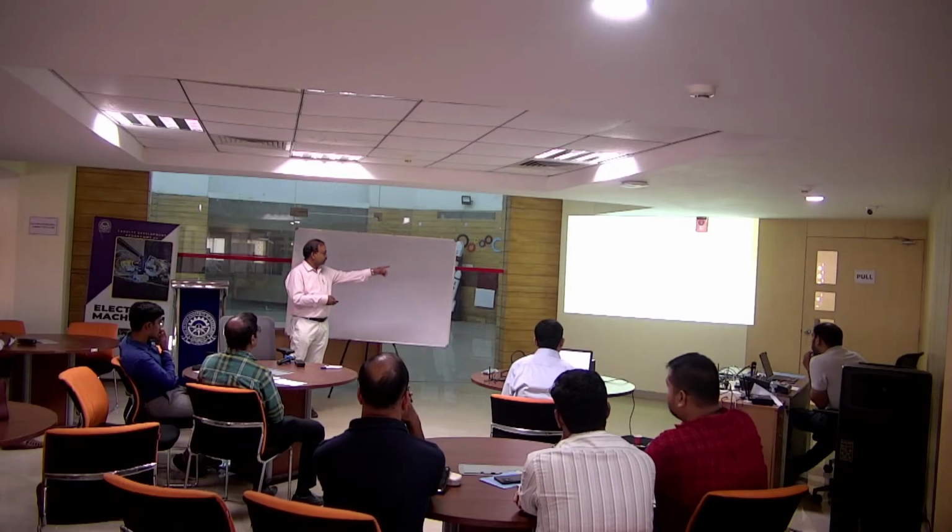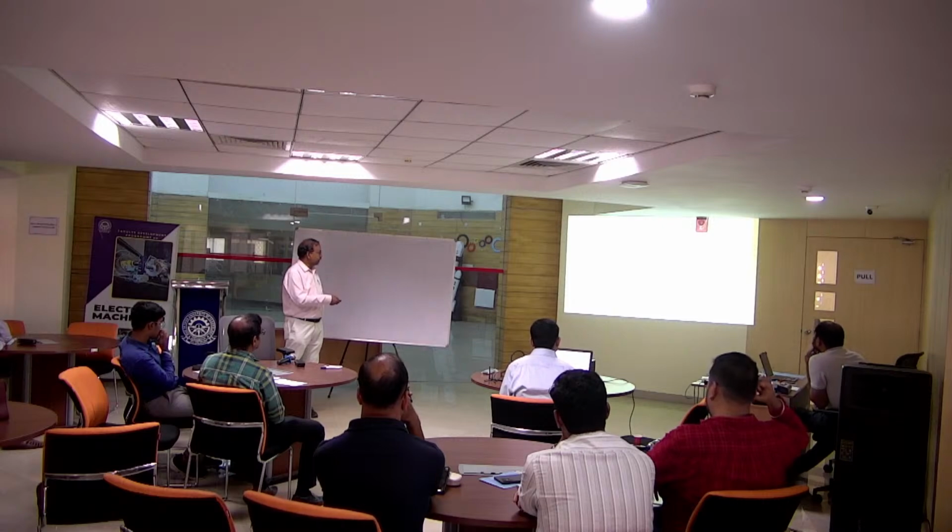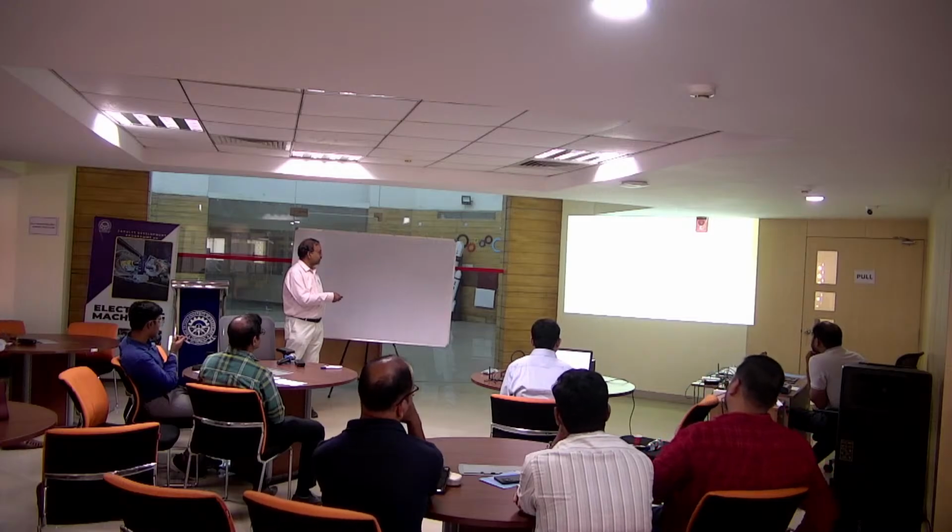So this is the speed versus torque curve. The y axis is speed, x is the torque. This is the starting torque and this is the synchronous speed. The motoring operation is here. If the speed is more than the synchronous speed, it will act as a generator.